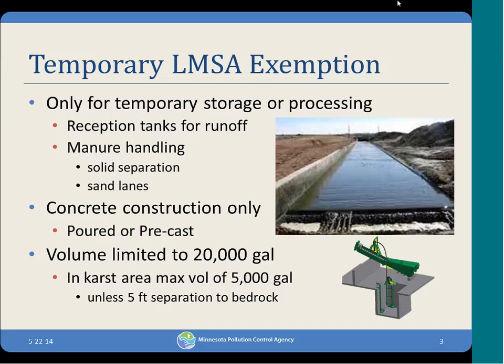I don't think we can require them to increase the pad. The problem is if the liner does get breached, they are in violation, and we have to go through enforcement at that point. So it's one of those catch-22s. The first place I'd start, like you already mentioned, is have them talk to their contracted pumper and see if they have any other equipment they could bring out. And in future construction, maybe have the owner discuss with who they're going to contract with on the equipment they have. The equipment's getting bigger too, and these older basins might have smaller pads.